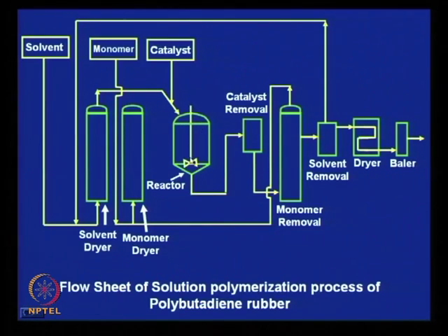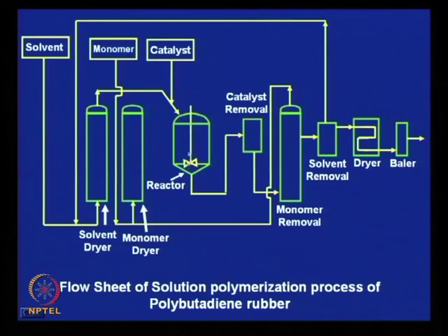Here this schematic of a stirring unit is required for homogenization of the mass in a solution polymerization for proper heat transfer, and details are not shown over here. It can have jacketed cooling or cooling coil inside. Inside there may be baffles, all those things. Then the monomer is converted to polymer containing the catalyst, say sodium amide or other those catalysts are used for polymerization.